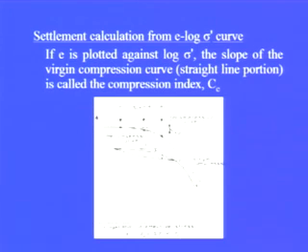Now when we unload it and when we reload it again, then we can say that this particular curve from here to here belongs to the over consolidated clays, and after that it merges with the normally consolidated clays. So over consolidated clays are those clays which have been subjected to the pressure intensity larger than the present pressure intensity.